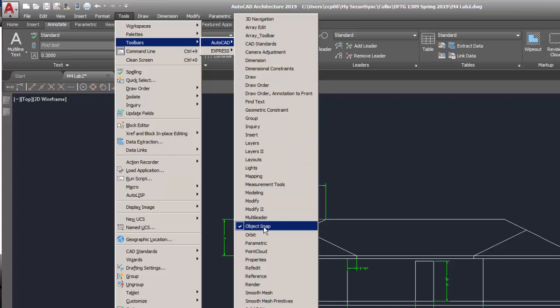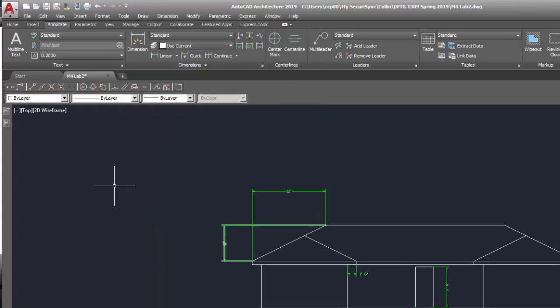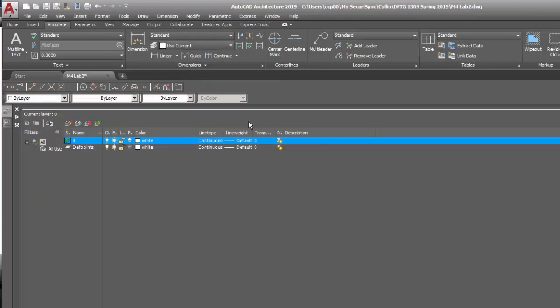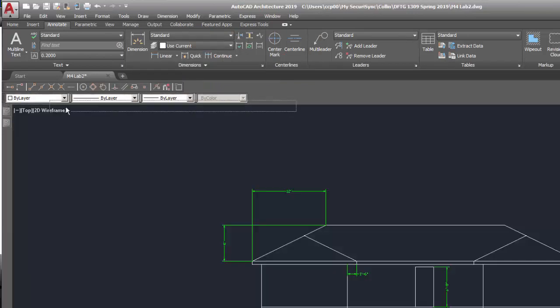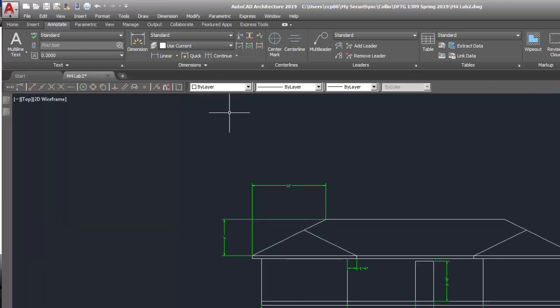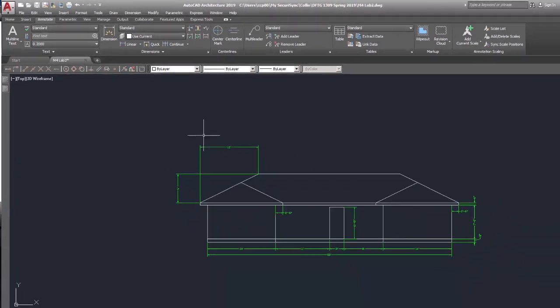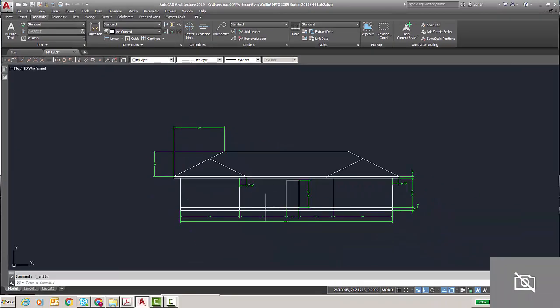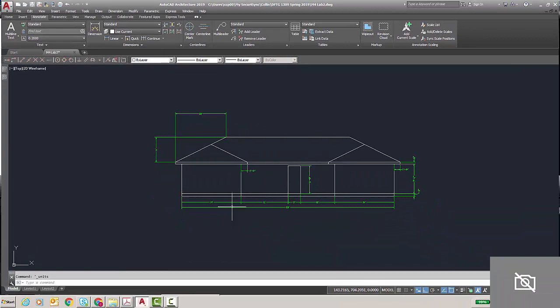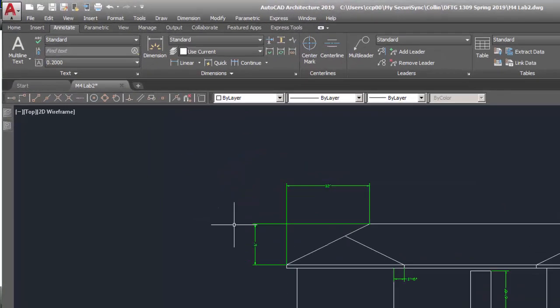Click on the O-snap, make sure there's a check by O-snap, and then down below, click on Properties. It puts it right underneath my toolbar. If I grab it to the left, I can drag it and place it up there. What this allows us to do eventually is to click on some items and change the layer or the colors as we need to.